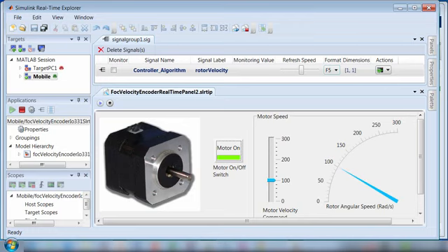You don't want to have those things pop up there. You'd like to have done a bunch of pre-work, which you can do with a rapid prototyping system, to find and fix issues ahead of time. The rapid prototyping system makes it very easy for you to see and log internal signals of your application and quickly turn around design iterations. So for us, that was a huge benefit.